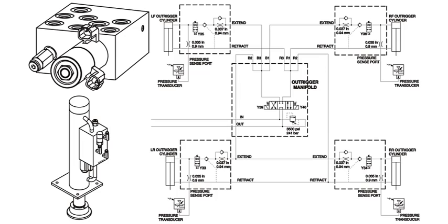The outrigger manifold houses a 3-position 4-way solenoid-operated valve used to direct pump flow to the barrel end or rod end of all 4 outrigger cylinders simultaneously. The outrigger cylinders have individual 2-position 2-way solenoid-operated valves in the barrel end. These valves are activated when the control system determines that the individual cylinder should extend or retract, providing individual outrigger cylinder control for auto-leveling. These valves serve as holding valves to support the load of the machine with the outriggers deployed. A pilot-to-open check valve is placed behind each of the holding valves as a redundant safety valve to prevent drifting and to meter the flow out of each cylinder when retract is operated.